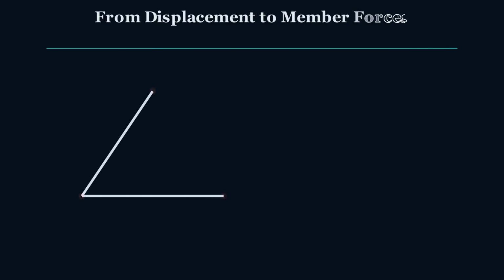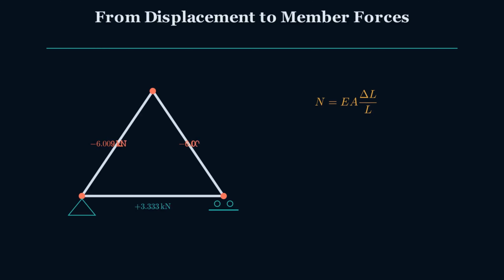The displacement solution is not the end of the analysis. We also need the axial force in every member. Member force comes from the member's axial deformation. Positive force represents tension, while negative force represents compression.